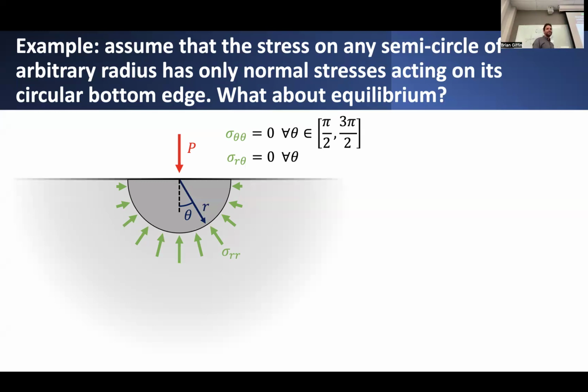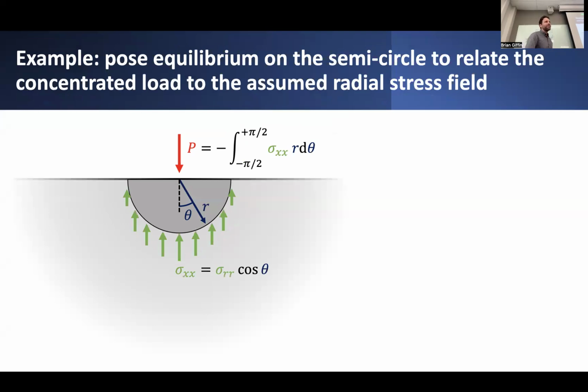It's semi-plausible, semi-realistic. This is essentially how the book goes about deriving this. We also have to impose some constraints on what this assumed distribution of stress needs to be, such that it is in equilibrium with that applied point load. So we have some loose constraints on what this stress distribution has to look like, just so that it balances with the applied loads.